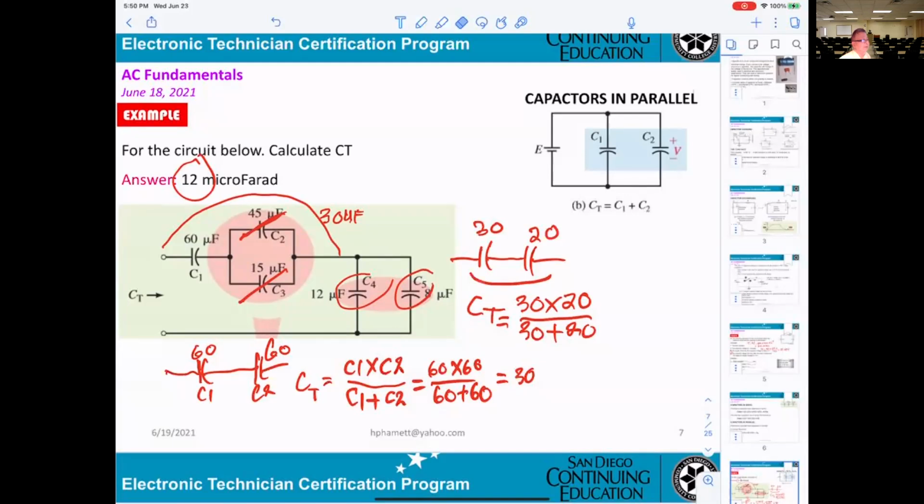Okay, any question regarding this problem? Yeah, I just have one. The 60 microfarads that's in series with the parallel ones, and it's all straight connected, you can treat it like it's just one unit, and then do the same kind of divider thing with the next series and parallel. Yeah, that's a way too easy to do. Don't try to combine everything, and that gives you a more complicated formula. We don't want to use the formula 1 over C1, 1 over C2 so far. This is an easier, simple way. Okay, thank you. You're welcome.